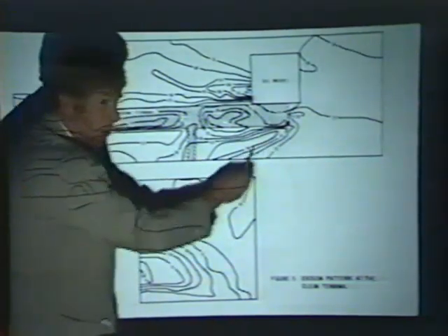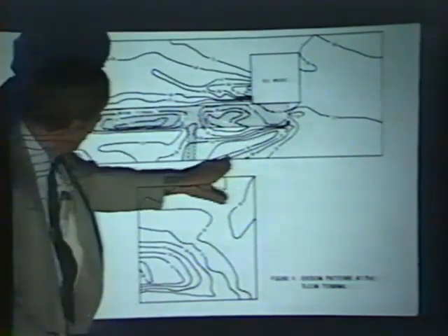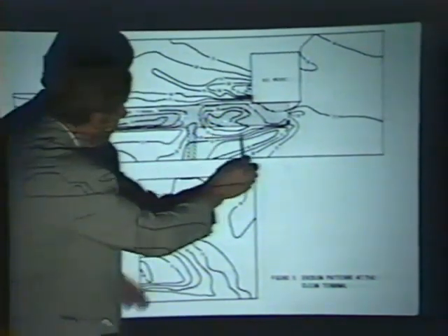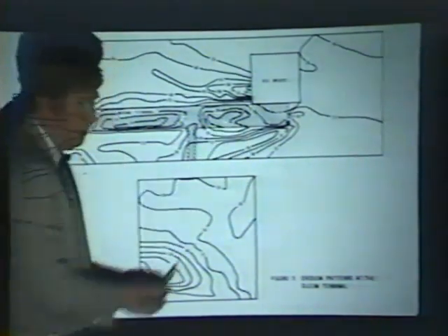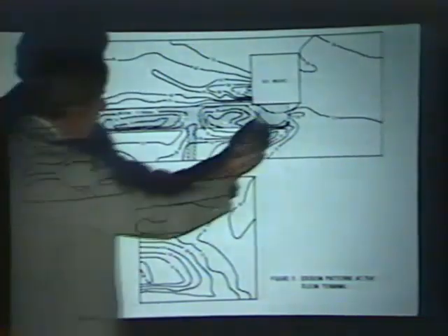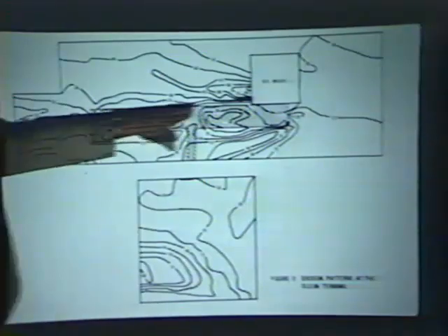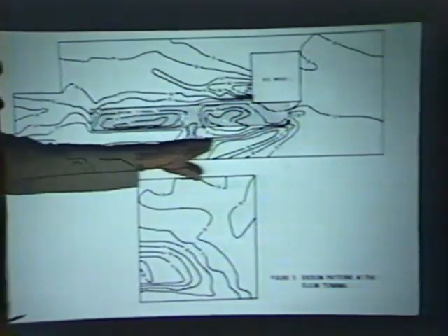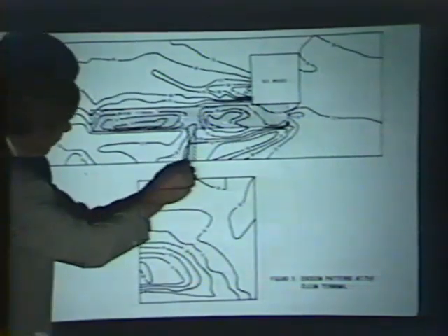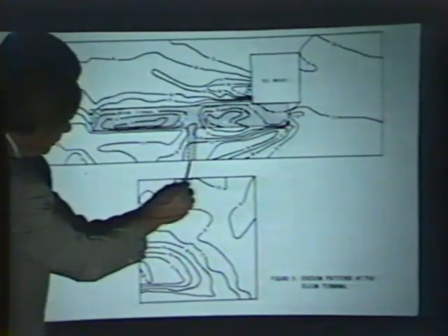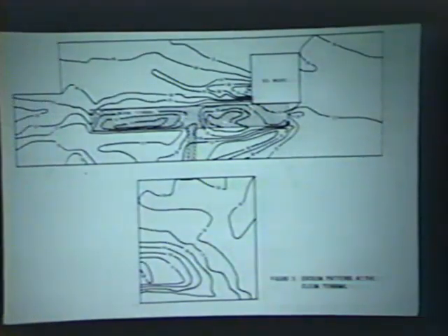So what's needed is some kind of a structure on the end here that would make these scour holes parallel to the wharf. In addition, the piles under this trestle coming out here cause sedimentation back in this region, but not too much because of the strong currents here. So their main problem is that they just have a blunt end on the wharf, and it diverts the water away from the face of the wharf so that they have to dredge.